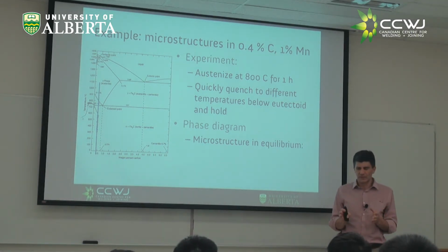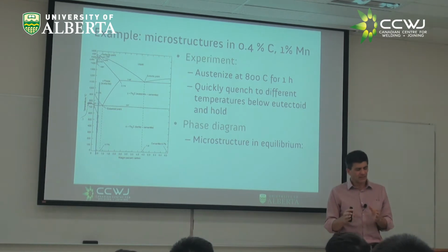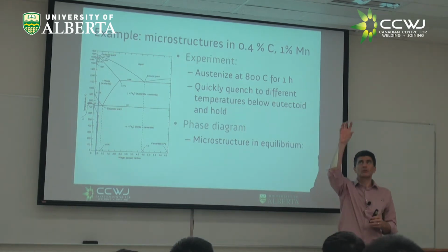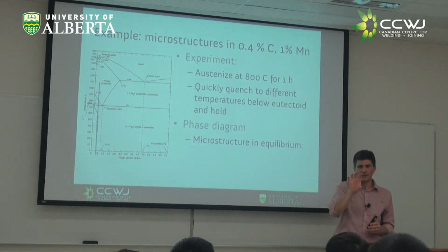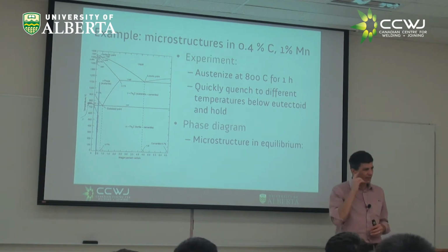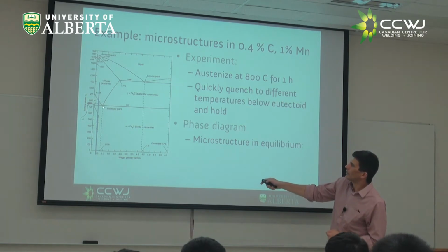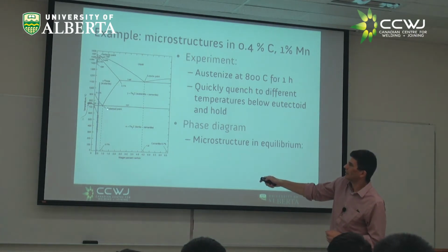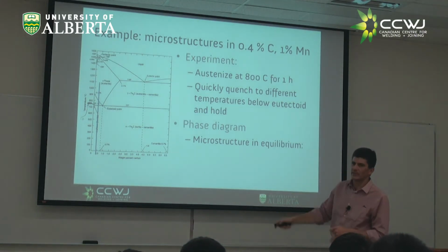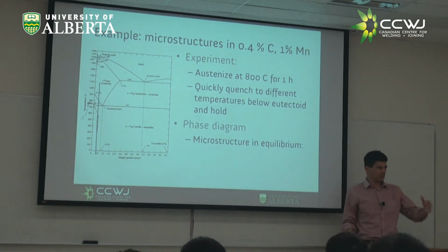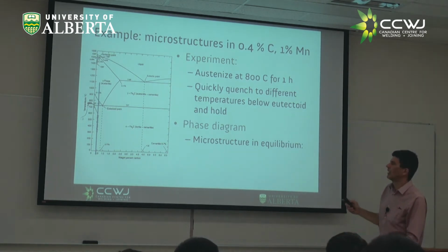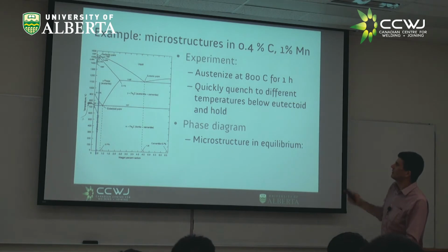So I want to discuss the same crazy heat treatment of holding to austenite, then quenching, holding it in a salt bath at different temperatures, right? You'll never do that. Crazy experiment, but I say an experiment that helps us think and understand, right? But let's do it not with a eutectoid steel, not with a 1080 steel, but with a 1040 steel. That is commonly available, often welded.